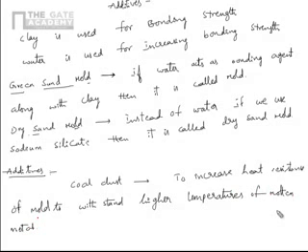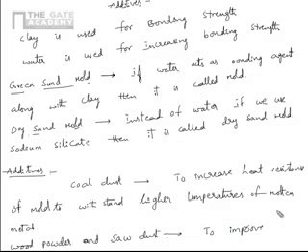Next one is wood powder and sawdust. The powder which is coming from wood or sawdust, in sawing it will be wood powder only. It is used to improve collapsibility of the mold. What is collapsibility?